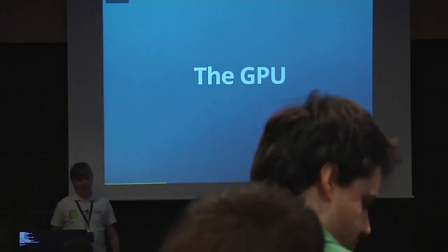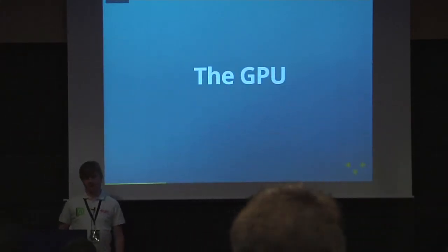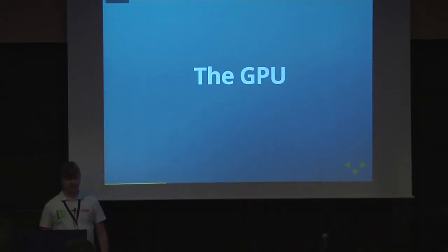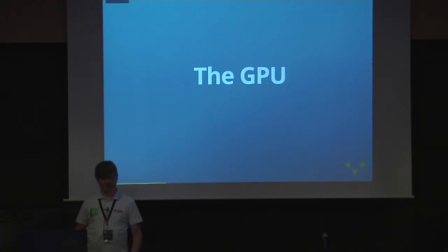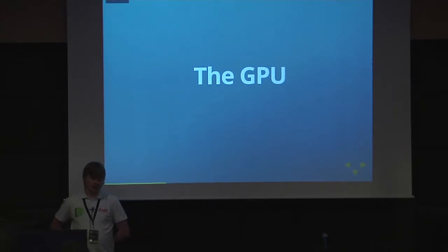Which I guess brings us to my next point. Something very important for Qt 5, especially on embedded, is the GPU. With Qt 5, we actually take full advantage of the GPU, unlike Qt 4, which made it quite difficult to actually use any graphics acceleration you had. But here we're using OpenGL ES 2 and offloading as much as possible of the UI code to the graphics coprocessor.